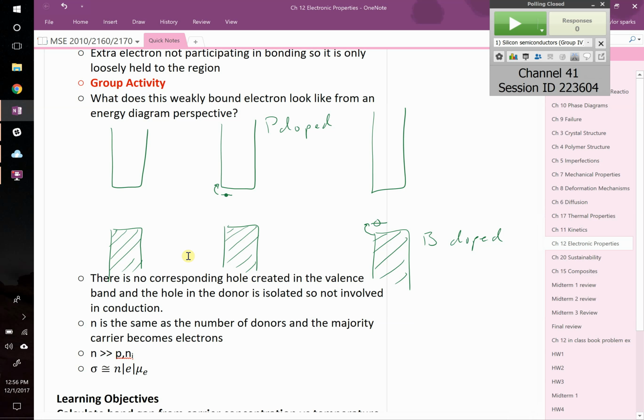John? So in an LED, is it a physical gap? Good question. No, that's not what the band gap is. This is purely speaking with respect to energy. We're talking about occupiable states at a lower energy, and then you've got a gap where you don't have states where electrons can occupy in terms of energy, and then you've got states where they can occupy. So in physical space, that electron's not moving, but it is gaining energy by going up to higher energy levels or not.